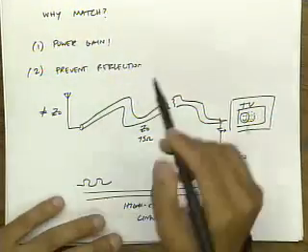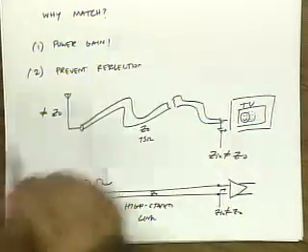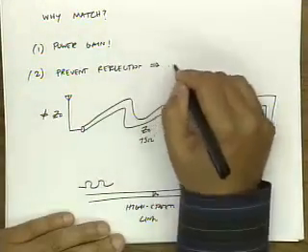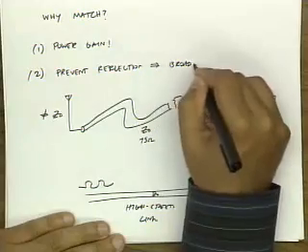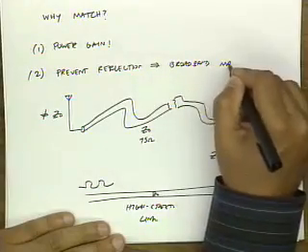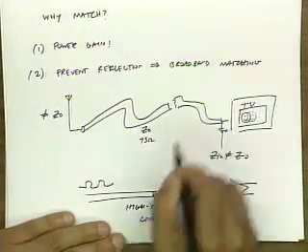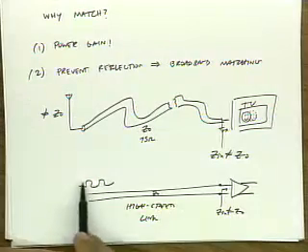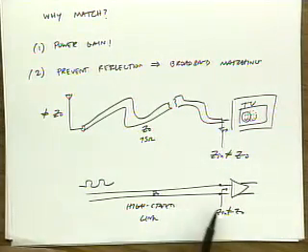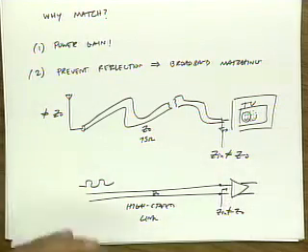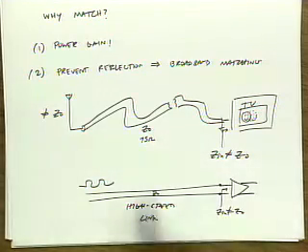And a big difference between case 1 and case 2 is that we really would like broadband matching. In this case, the data signal is broadband, it's high speed. So we would like to provide a termination from DC all the way out to, let's say, a few gigahertz, if this is a gigabit per second link.